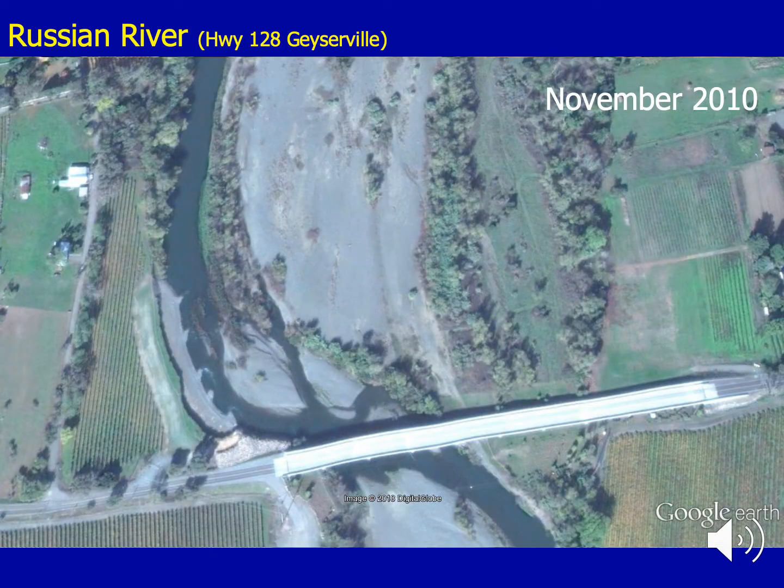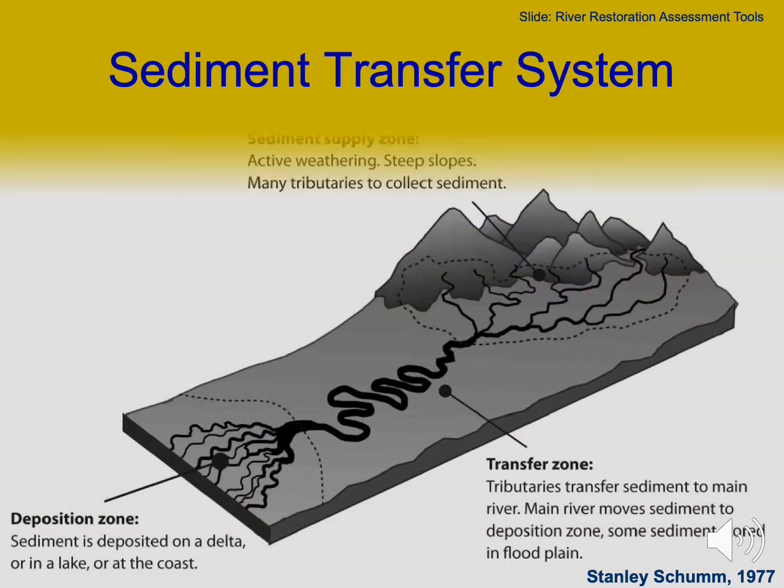Riprap this entire area up here. Put in some lateral deflectors here with riprap and kind of lock in the thalweg here. Again, the same problem. We have basically pinned the channel right there for the foreseeable future. And we sort of lost our lateral migration.